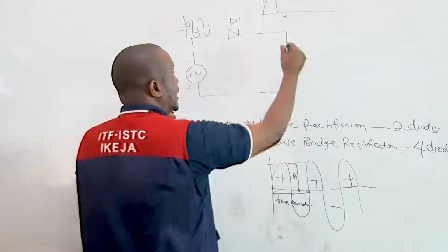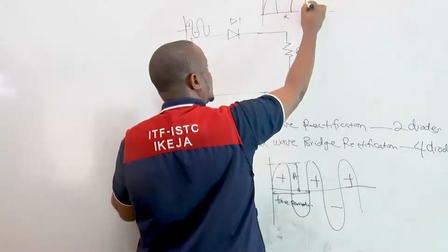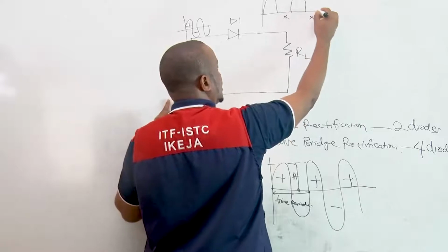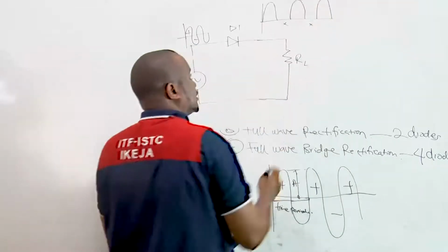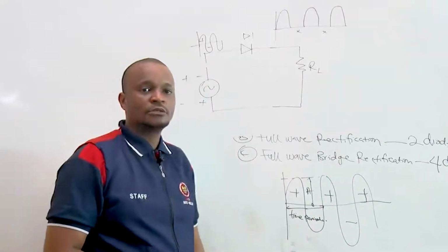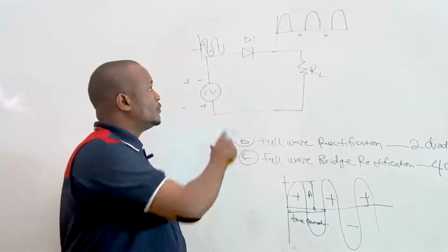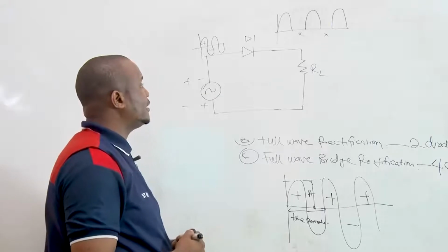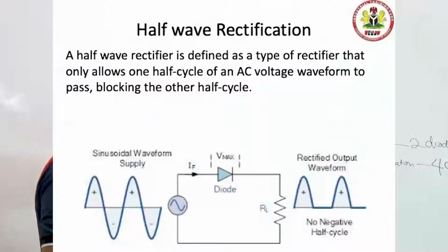During the positive half cycle, we have another conduction. During the negative half cycle, nothing happens. We have another conduction. So this is how the waveform from a half-wave rectifier will look like. So we have a series of gaps in this way.